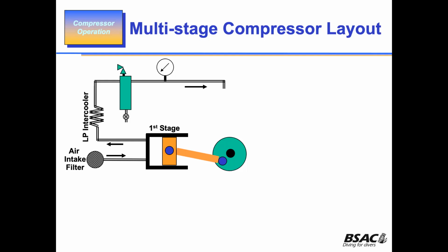You'll come across the term dew point. Every charge of air has its dew point. And if you take it below its dew point, the moisture comes out of solution, comes out of the air.